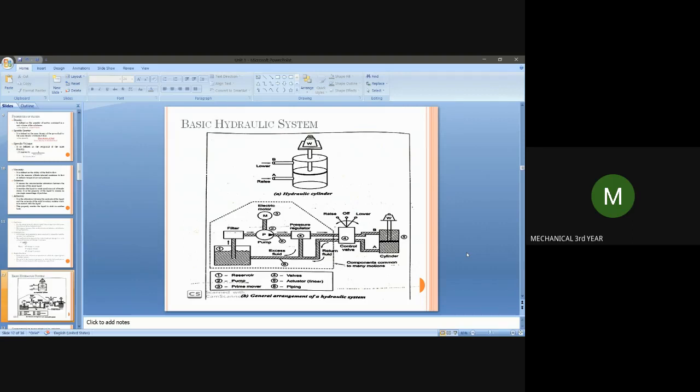It increases the pressure, and when compared to that of the reservoir, where the fluid is contained, it doesn't have that amount of pressure in it. So in order to increase the pressure, we are going for the pump. Even if the pump increases the pressure, if the system requires more pressure, this pressure regulator increases it. If the pressure outside the pump is somewhat less, the regulator takes the responsibility for increasing the pressure, and after that it transports the fluid to the valves.